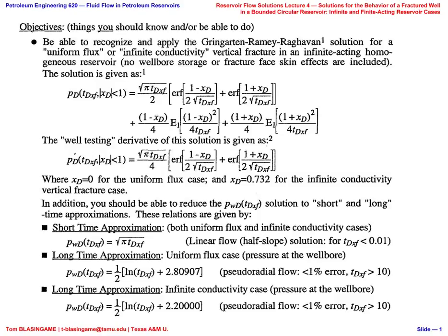It has to do with the stress planes. So there's all sorts of complications here. I'm telling you all this, I'm taking up your valuable time, because I want you to understand that the concept of a perfectly planar vertical fracture is a fantasy. Okay? If we want to have conductivity in that fracture, we're going to have to put something in it, more than likely.